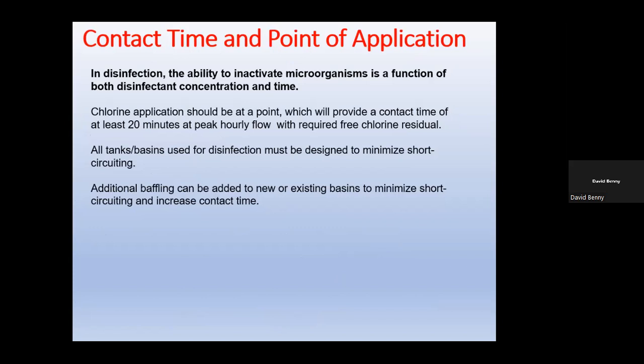The concept of contact time. All disinfectants work based on dose and contact time. For chlorine, some trainers will tell you 15 minutes, some will say 30 minutes. But because it's contact time and dose, you can vary one against the other. So you can have a high dose and a short contact time, which is not advisable, but in some cases you can't do anything about that, so you have to utilize what you have.